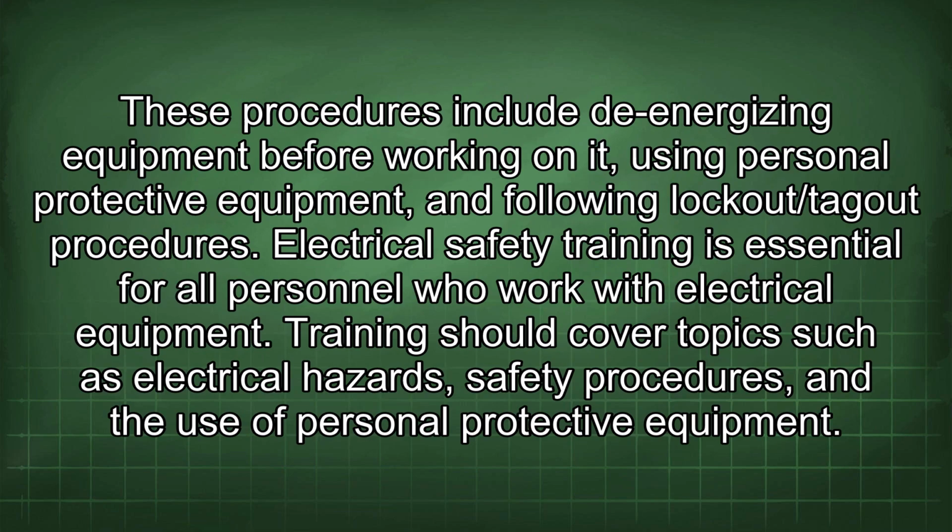Another important element is the application of appropriate safety procedures when working with electrical equipment. These procedures include de-energizing equipment before working on it, using personal protective equipment, and following lockout/tagout procedures. Electrical safety training is essential for all personnel who work with electrical equipment. Training should cover topics such as electrical hazards, safety procedures, and the use of personal protective equipment.